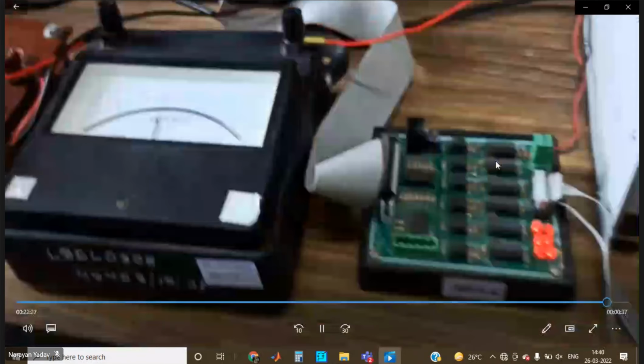The output data is, the output voltage is 49.6 volts. The output current is 112.2 milliamperes. The fundamental component of output voltage is 49.5 volts and THD is 1.8%. Now we will change the load again.